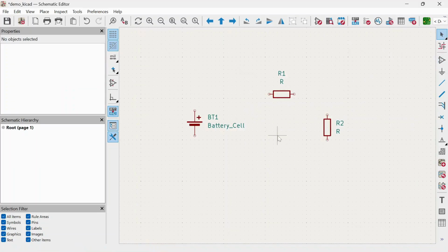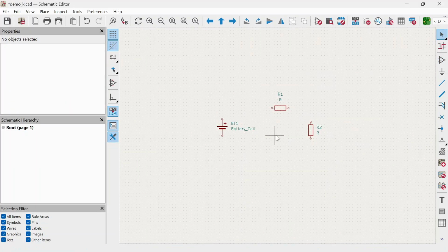You can zoom in by scrolling in. It will zoom the circuit in. Now if I go to the edge of this component, it will become like a pencil, which is basically to make the connection. Or you can click on this draw wire option. That will also make a pencil to draw the wire. So I'll click on this edge, take the wire where I want. Let's say I want to connect it to this resistance.